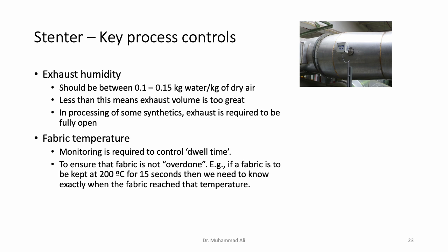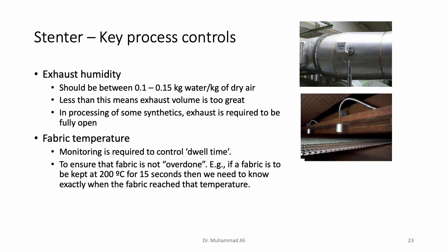So normally in modern machines, again, these systems are automatic. So fabric sensors, which look something like this. As I mentioned, these are non-contact sensors. They detect or measure the fabric temperature without any physical contact with the fabric. These sensors are, of course, connected to the machine controls. In modern machines, if these sensors detect that fabric temperature is less than what you want it to be, then the machine controls will automatically increase the burner output or make necessary adjustments to increase the fabric temperature.